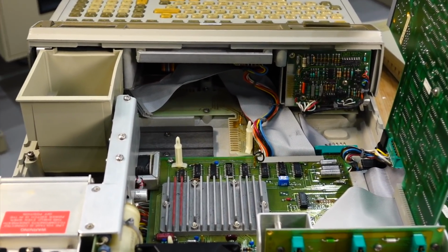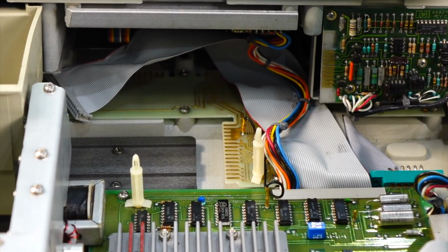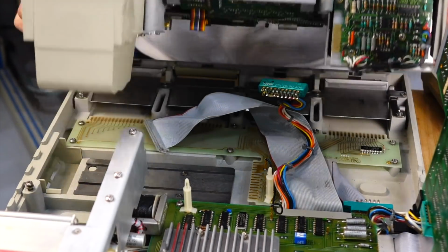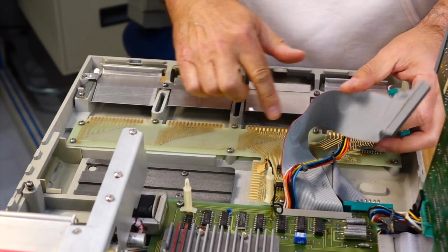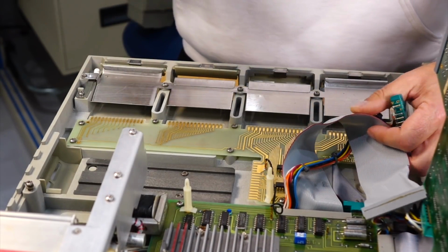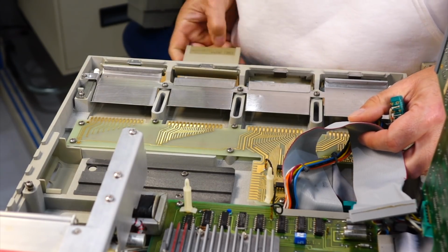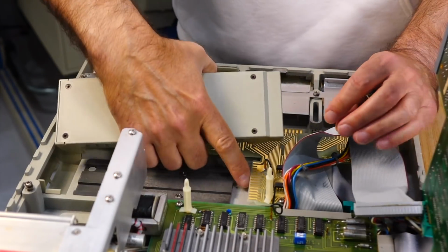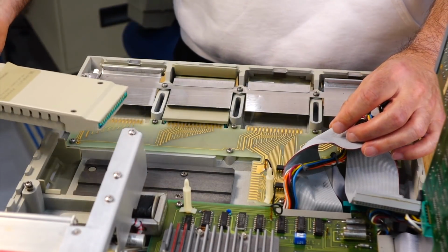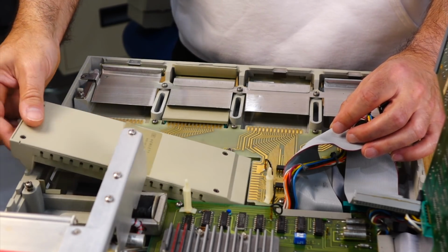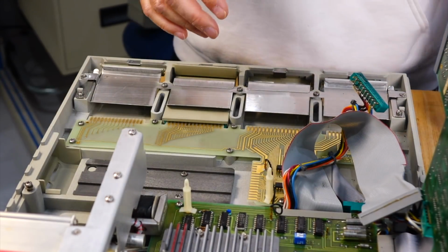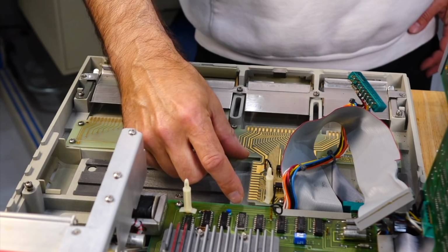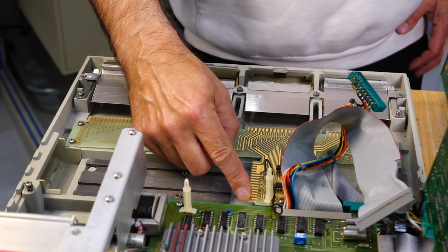However, over there is a remnant of a connector that was used in the first version of this machine, the 9825A. So if you take the keyboard off, you see that we have a whole bunch of connectors, and those were used for ROM cartridges, the optional ones that you put in the front of the machine, right here. But this big one was used for the system ROM in the A. The system ROM is a drawer on the side. In the B and the T, the ROMs are over here, so we don't need it. So my thinking is to find a connector that slides on there and use that to probe the bus cleanly.